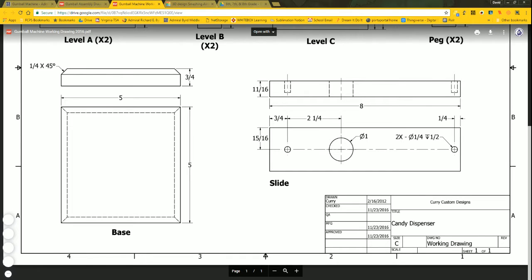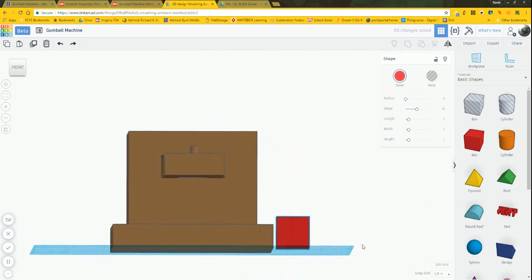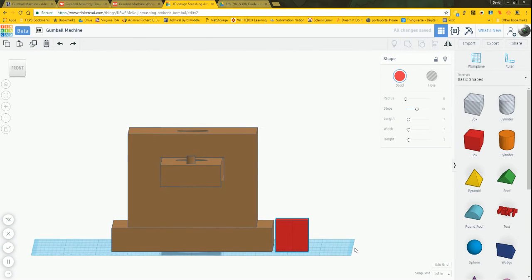and 1/4 of an inch deep here. So I played around with different ways to do this, and here's what I think is going to be the easiest. If your work plane's not clear at the bottom, reset it so it is. Let's bring out a box and just kind of drop it down in here for now. And what I really want to do at the moment, I'm going to make 2 boxes, one for sizing and one for the actual cut.